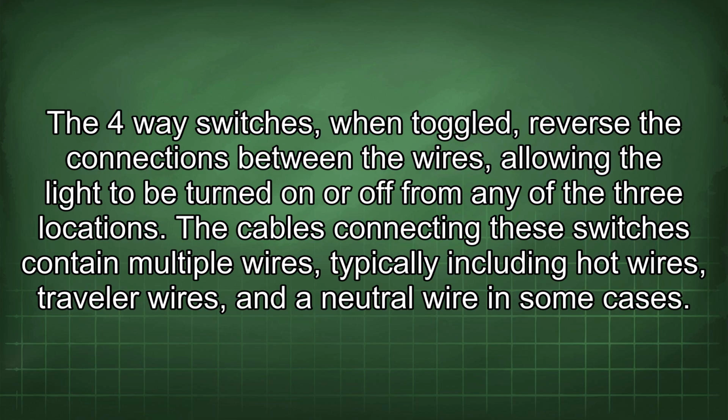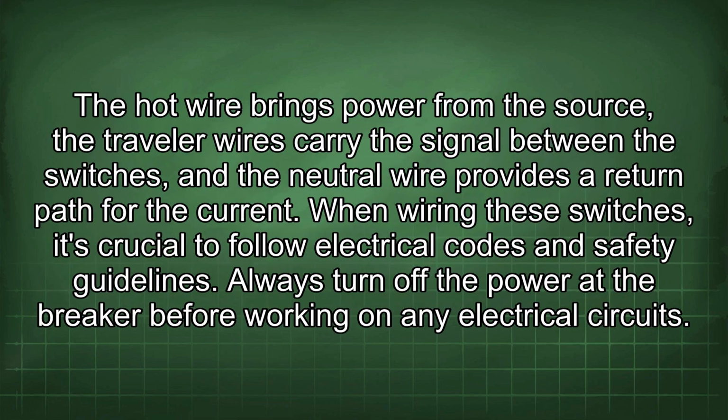The cables connecting these switches contain multiple wires, typically including hot wires, traveler wires, and the neutral wire in some cases. The hot wire brings power from the source, the traveler wires carry the signal between the switches, and the neutral wire provides a return path for the current.